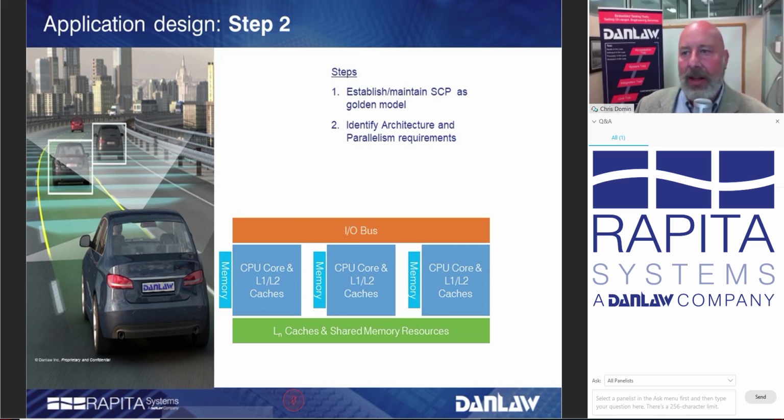More significantly, you're probably going to be worried about the concurrency requirements, and this is a little bit different than parallelism. Concurrency usually refers to tasks that look like they operate in parallel, but in fact they're interleaved. The execution steps of each thread might be interleaved with others on different cores. So there's basically a distribution of tasks between the different cores. They look like they're running concurrently, but in fact they're still subject to the tasking provided by the real-time operating system on the single core.